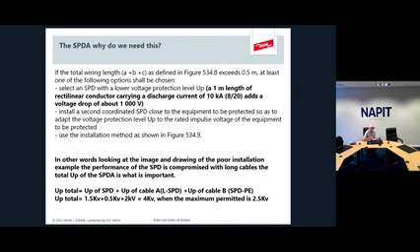And this is why we have to be very careful about the actual cable lengths themselves. Just 1 meter of cable adds a volt drop of 1 kV when I've got a 10 kA surge going down it. And that little equation down the bottom shows me the value of the total performance of the SPD assembly you saw in that image. So I've got 1.5 kV down the SPD itself. I've got the short cables, 500 volts there, and then the long earth wire, another couple of kV. So that's 4 kV when the maximum permitted value is 2.5 kV. So this gives you an idea of the sort of figures that we're going to be dealing with.